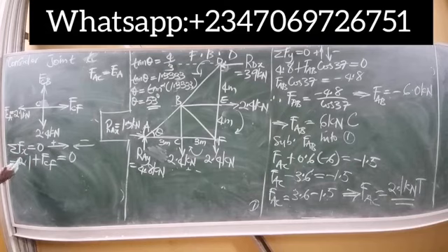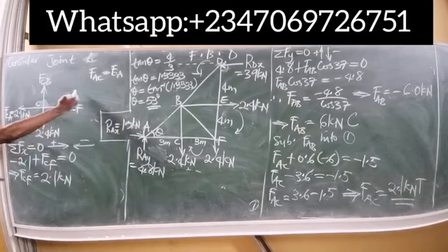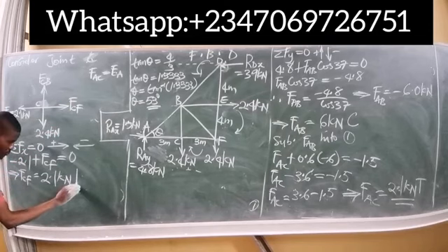If that's the case, then simply send minus 2.1 over to this side of the equation. That simply means that the force at joint C relative to F is equal to 2.1 kilonewtons. Remember, when a negative sign crosses an equal sign, it becomes positive. We assumed tension for this force and we're also obtaining positive, so it means the direction is also in tension. So it's correct. The direction assumed was correct. So the member CF is in tension.